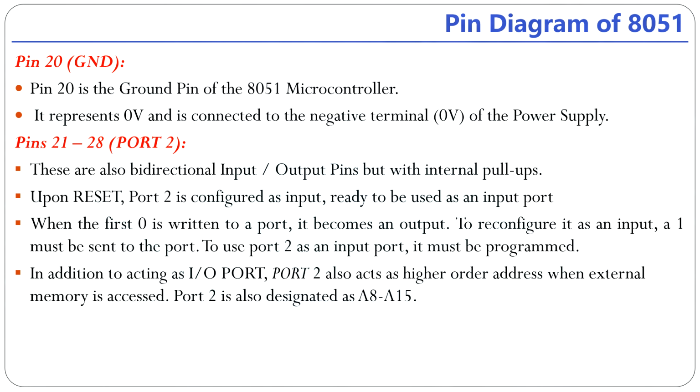Then pin number 20 is the ground of the 8051 microcontroller. It represents 0 volts and is connected to the negative terminal of the power supply. So you need to provide 0 volts to the 20th pin. Then pins 21 to 28 are provided for port 2 in standalone mode, and in extended mode it operates for generating the higher order address, that is from A8 to A15.